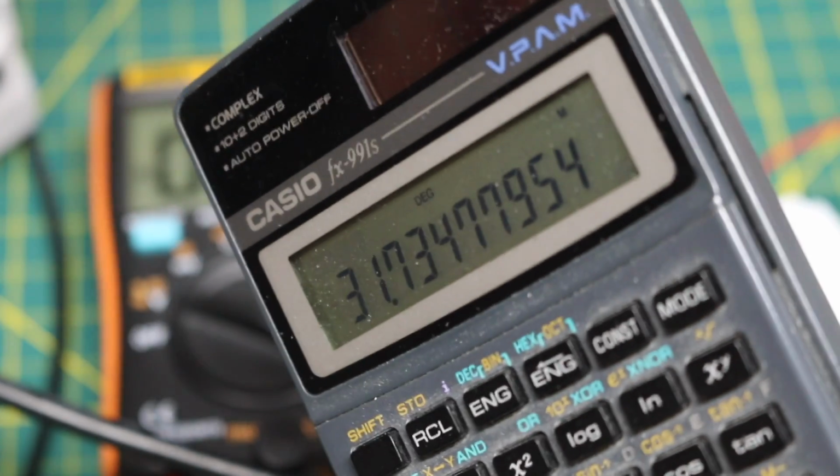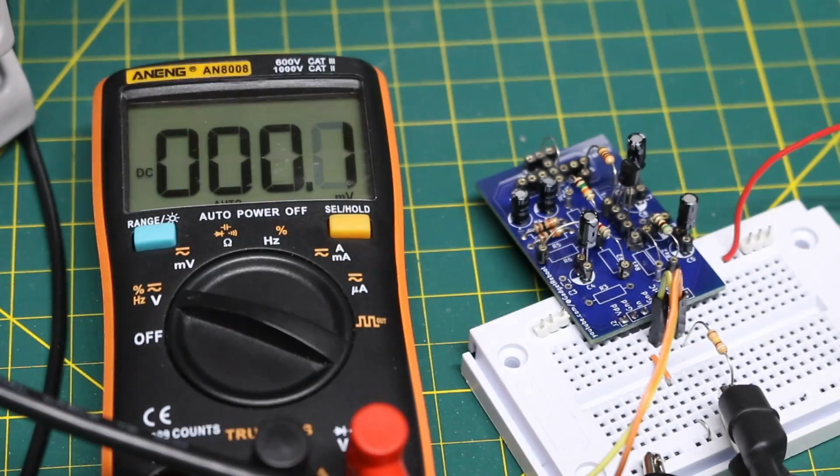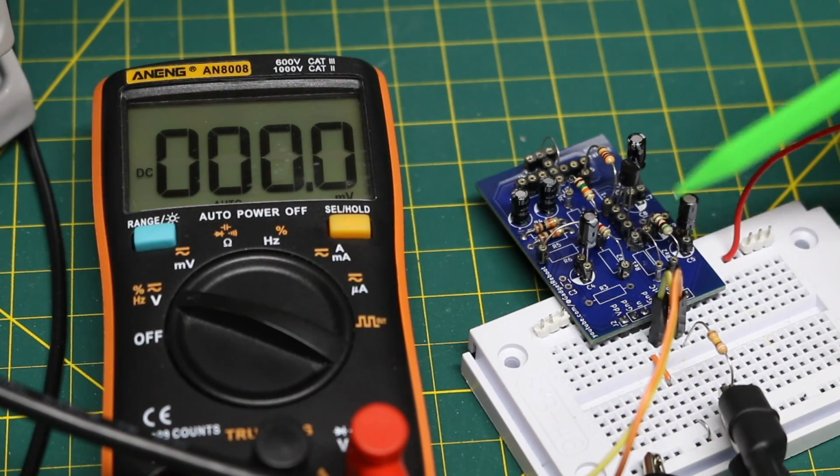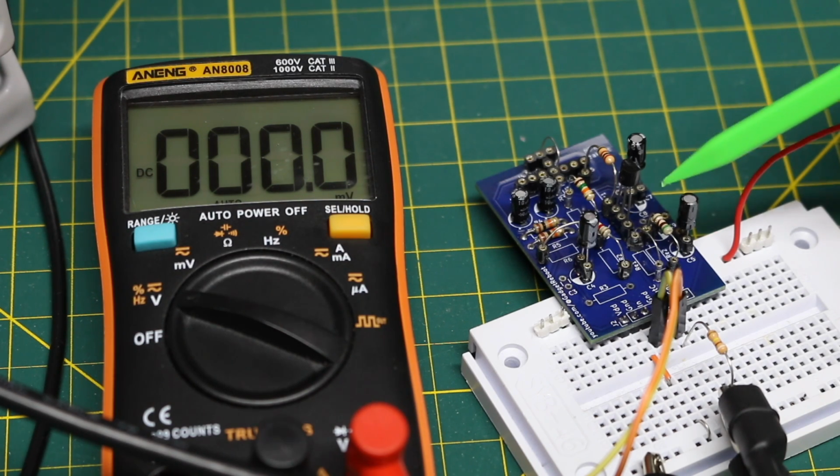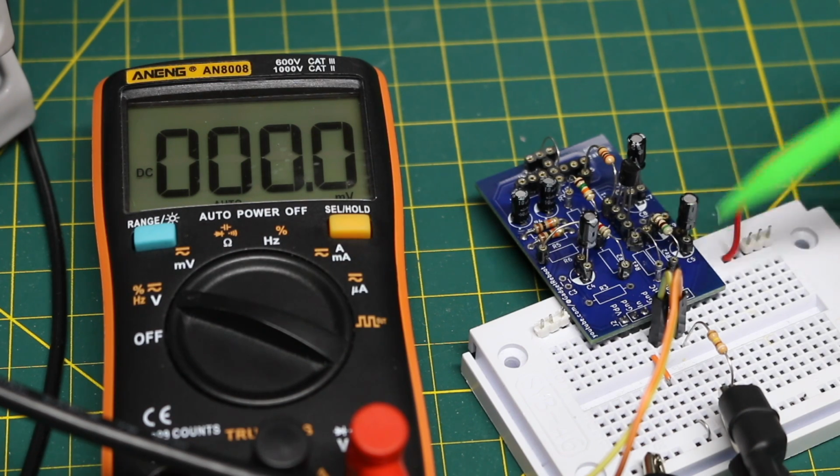And 31.7 ohms is relatively small, so now we need to factor in properties of the transistor, taking into account the transconductance. We need to calculate the impedance we're seeing looking into the emitter of the transistor and put that in series with this external 31.7 ohms.